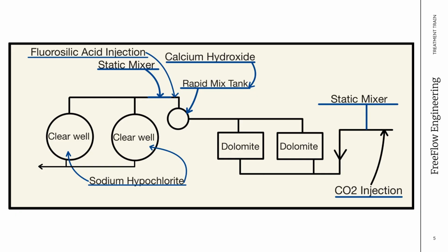The water will flow into the two clear wells, where sodium hypochlorite is added, which will disinfect, reaching a 5 log removal, and will leave residual disinfection.